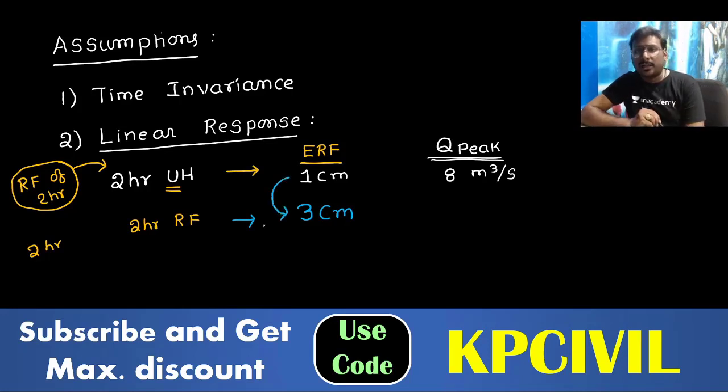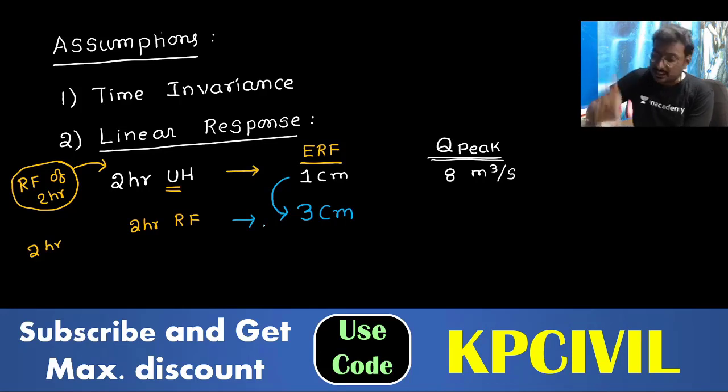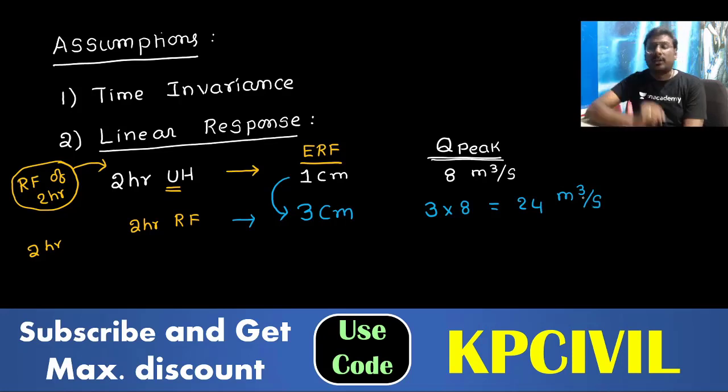For 1 centimeter depth, peak discharge is 8 meter cube per second. What is peak discharge for 3 centimeter depth? Catchment area same, duration same, losses same, everything same. 3 into 8, so 3 times linearly increasing: 24 meter cube per second.